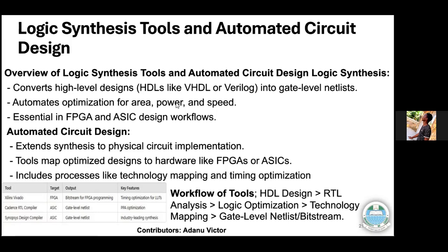Then for RTL analysis, we are talking about register transfer level analysis. Here we are trying to synchronize the timing, the timing correctness of the design. So when you are simulating, you need to be able to synchronize the timing of the HDL you're writing and what you are trying to actualize at the end of the day. After that, we go to logic optimization.